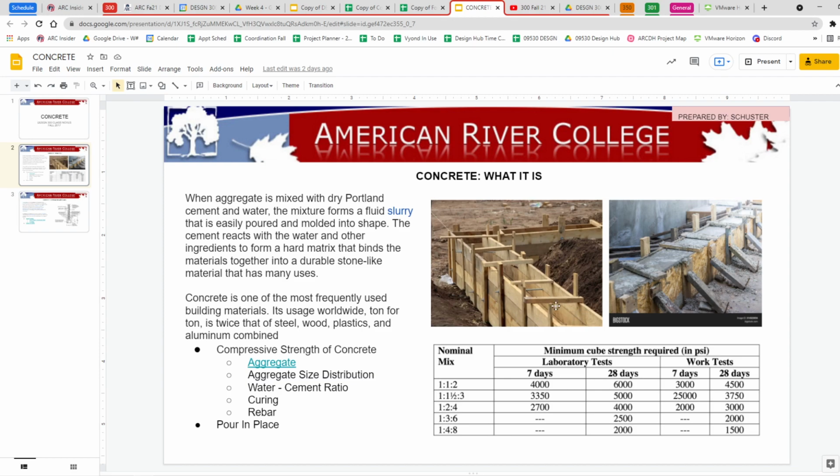Forms have to be pretty good. You can see right up here, it's hard to see, but there are some little strings. Those are leveling lines, and so they level you and get you lined up properly. And there's some skill to doing this. If you think that you just go out there and hire anybody to do the forming work, you're mistaken.